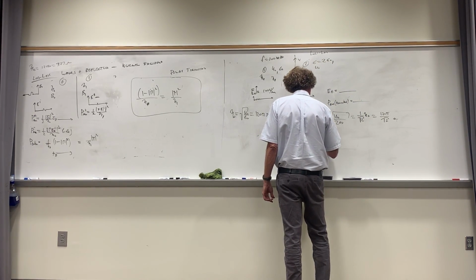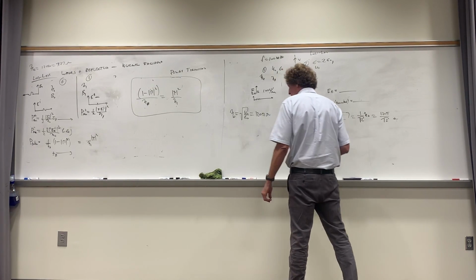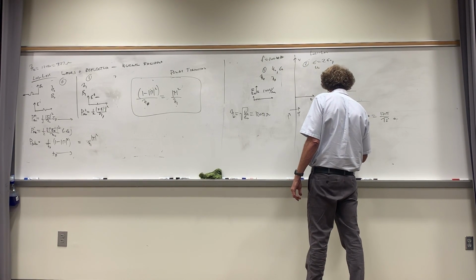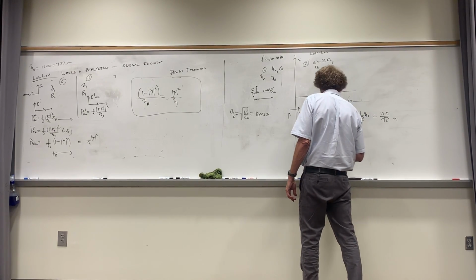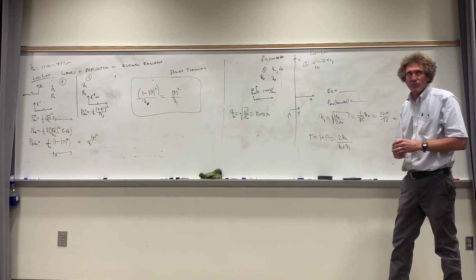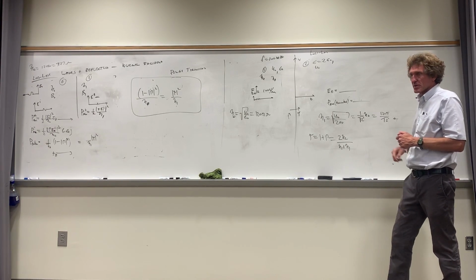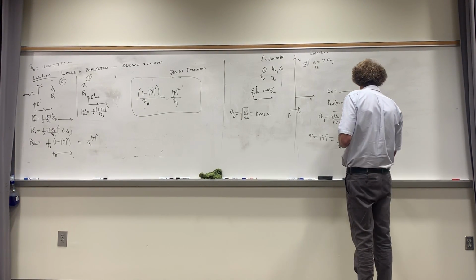Well, it's 1 plus the reflection coefficient, if that helps. And it's also 2 times eta 2 over eta 2 plus eta 1. It's always twice the impedance you're going into over the impedance you came from plus the impedance you're going into. What's that going to be?